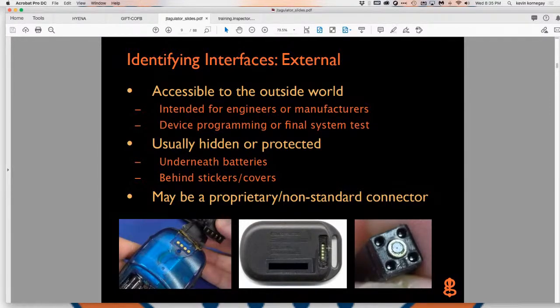In the middle, this is a keypad. And what's this on the right? I don't know what that is on the right. But you can see this is usually the JTAG port, and that's a good indication. The JTAG port has 4 key signals, and this will usually give you an indication that, oh, gee, this may be a JTAG port.